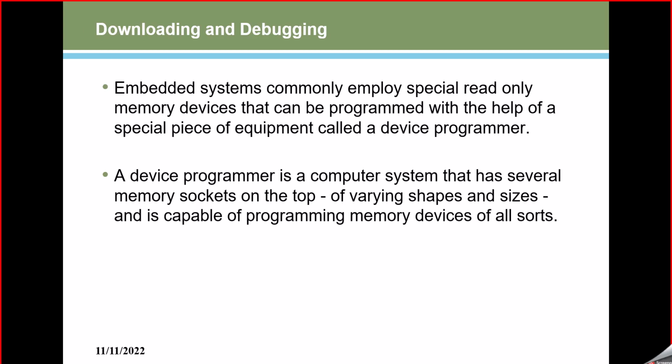Once it's saved, then you can start running it. So how do we save it, or how do we program that controller with our output file? Generally we use a separate external device to program the code inside the microcontroller or microprocessor. The software for this is ISP programming, such as Flash Magic. Samples of downloading software are Flash Magic, Flash Utility, or even JTAG.